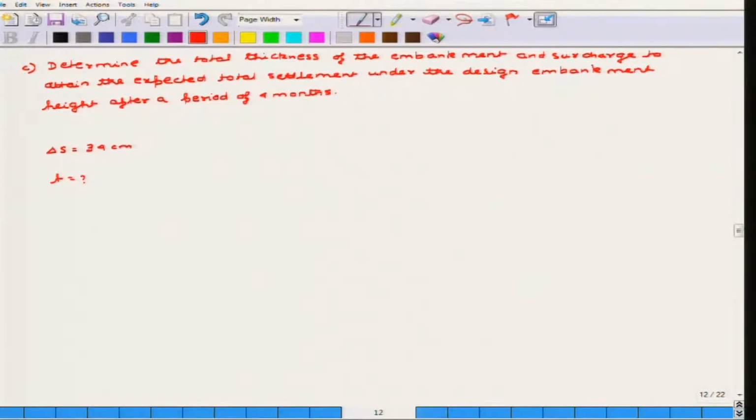Theoretically, you know from the consolidation curve that the time taken is infinite, because this is an infinitely long settlement, but general practice is that 100% settlement is obtained when U is equal to 99.4%.